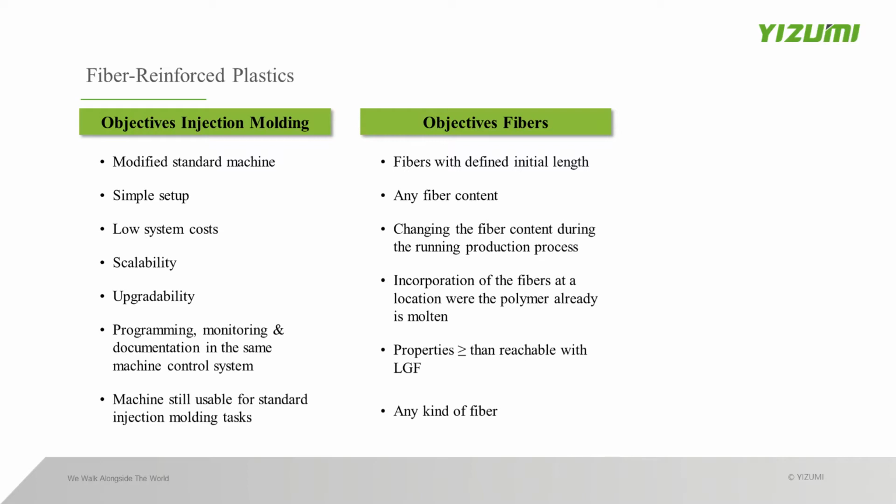Also, there is incorporation of fiber at a location where the polymer is already molten. This is because the position where we feed the fiber is in the middle of the injection unit, in the middle of the injection cylinder. I can show the photo later, so maybe you can have a clearer concept. And we can also get final part properties better than with the long glass fiber pellet.